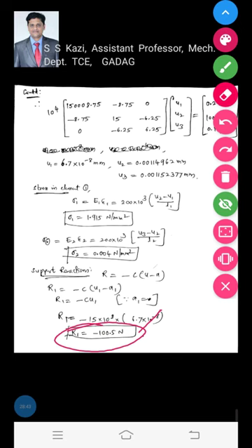This is how we can apply the penalty approach and elimination approach. In the examination, if you are asked to solve problems on bars to determine the nodal displacement, stresses in each element and support reactions using FEM, then you can use either the elimination or the penalty approach. If it is not asked specifically which approach has to be used, then use the elimination approach, that will be convenient for you.